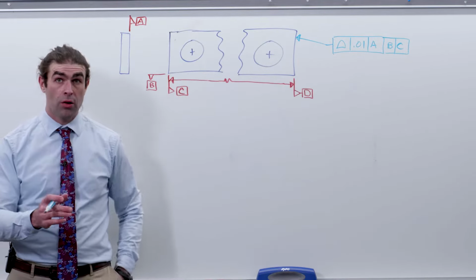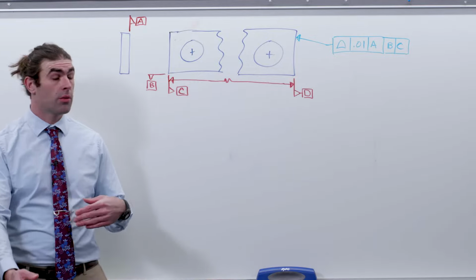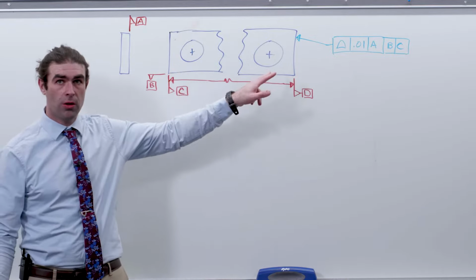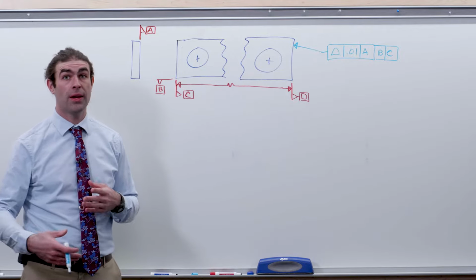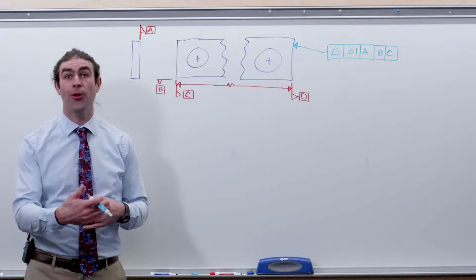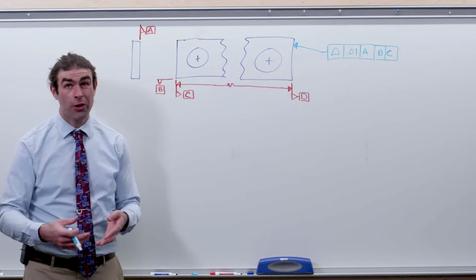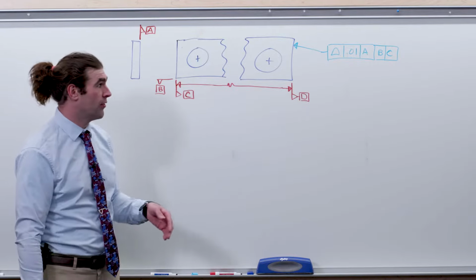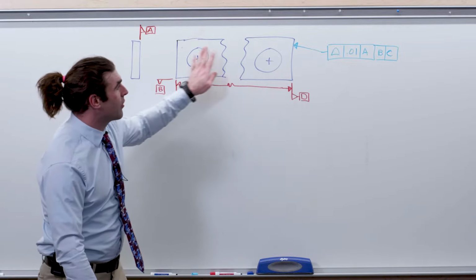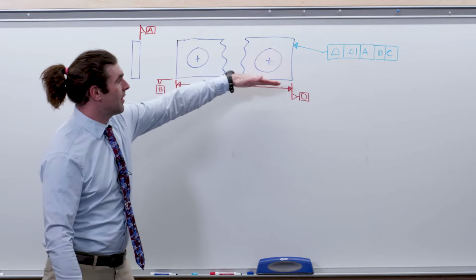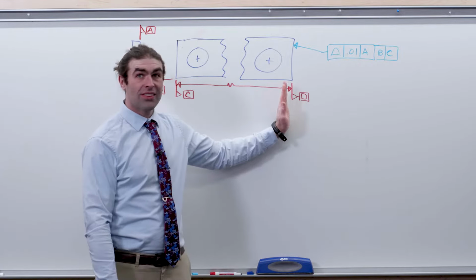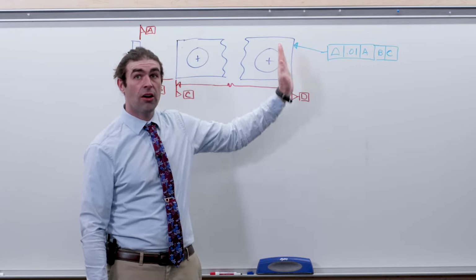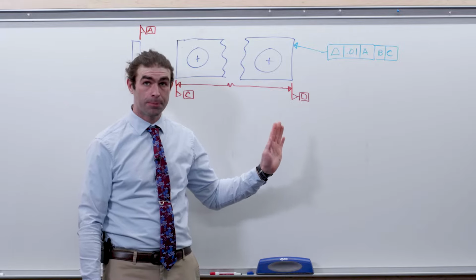So let's say we've got a really long part, right? We've got a hole on this end, a hole on this end. Again, all the details on this part aren't shown. I used this as an example to talk about multiple datum reference frames. It'll work just as well for this profile discussion. Datum A is the large flat surface. Datum B is this surface here. Datum C is here, and we're going to establish a datum D on this side of the part.